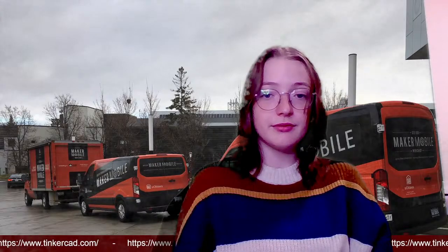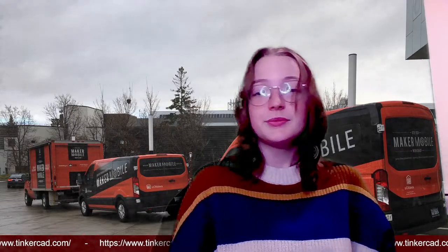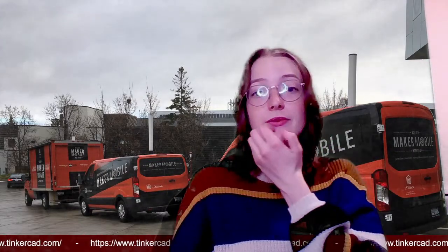Obviously when we're printing something, we have to take into consideration things like gravity or the weight of the object or the weight of the filament. But otherwise, it's pretty limitless. The only thing is it takes a lot of time. 3D printing is really cool, but if we want to 3D print something that's very big, it will take us hours upon hours. Small prints, if they're pretty simple, can take between 20 minutes to an hour, but it can easily go way over that when we're printing something that's more complex or bigger.